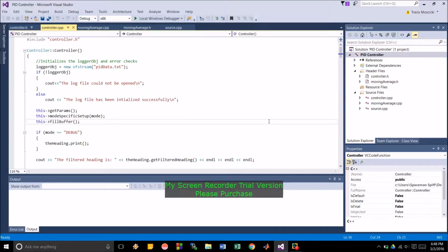So now what's a PID? A PID is going to have a slower rise time still, and less overshoot. It's going to oscillate a little bit, and then it's still going to find the balance. It's going to find that zero steady state error because it still has that integral term involved. So, all right, there are benefits to each one of these.